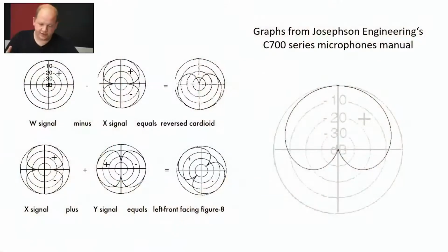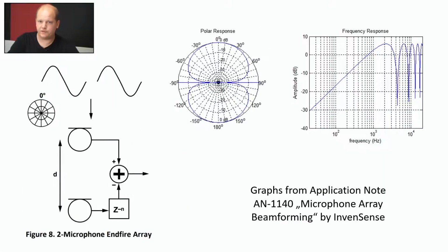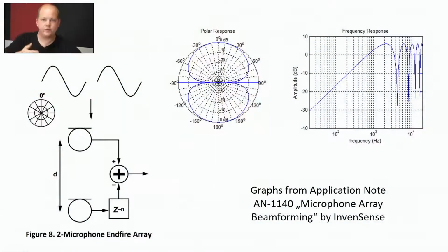Now, this is useful for stereo recordings and such, but for Ambisonics, I told you we also want the vertical plane. So now we need to find out how we can have a cardioid pattern facing to the top and to the bottom. For this, we actually use a technique coming from automotive or mobile phones, and this is the so-called end-fire array. So if you have two omnidirectional microphones at a physical distance, so for example, in our microphone array, we have the distance between the two capsules, we can have a figure-of-8 in this vertical plane, in the z-axis, facing from the top to the bottom.